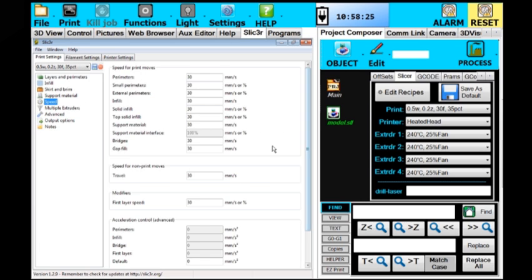The speed, we don't recommend running the printer at more than about 2 meters a minute. So our default recipes indicate 30 millimeters a second or 1800 millimeters a minute. For some materials and some G-code, based on how the printer is moving, we actually recommend going slower.